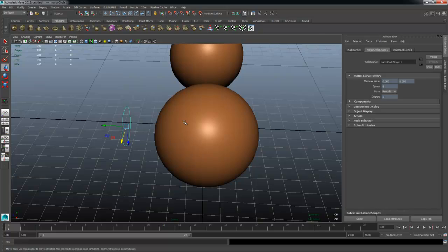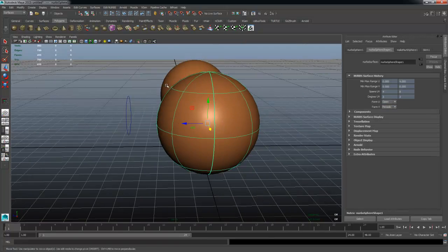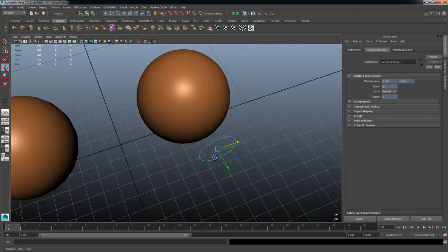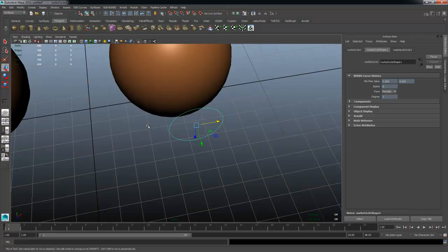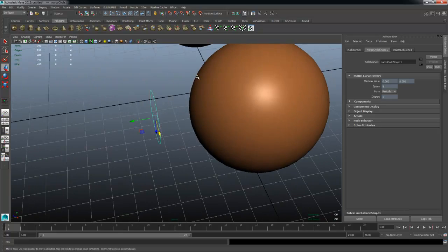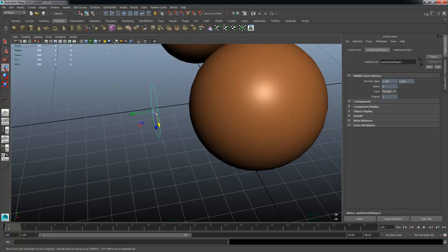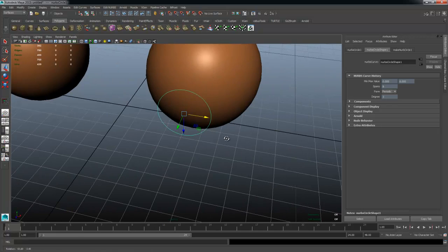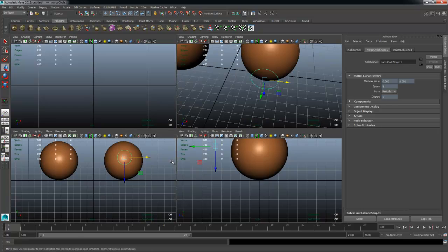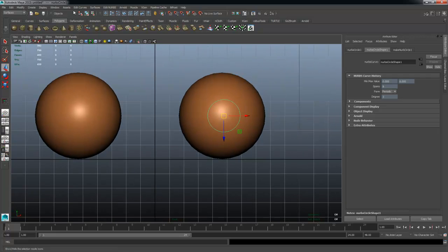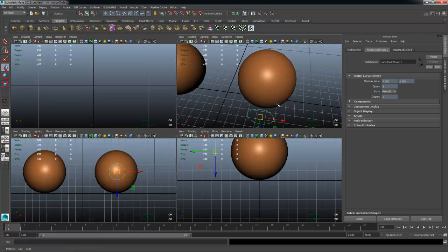So what's going to happen now is I'm going to use the circle to project the curve itself onto a 3-dimensional model that has volume and shape to it, while a curve is a 2-dimensional axis. So it's going to create an intermediate type of projection on the surface, and when I update this one on a 2-dimensional plane, the 3-dimensional projected curve will essentially update as well, which is very, very cool.